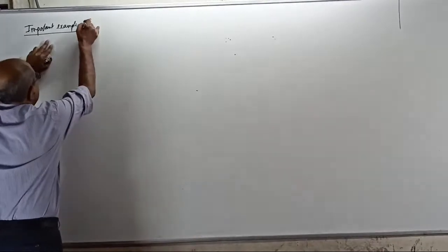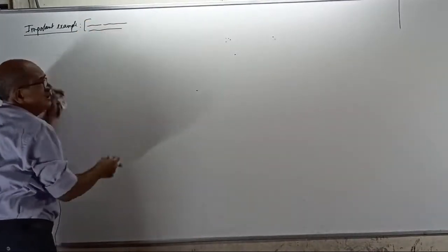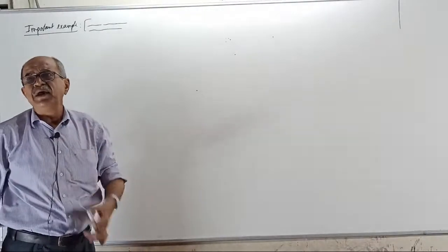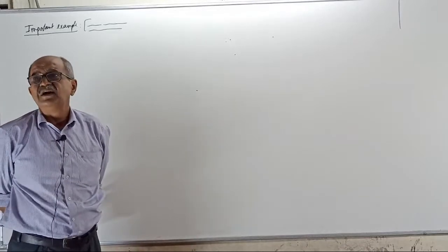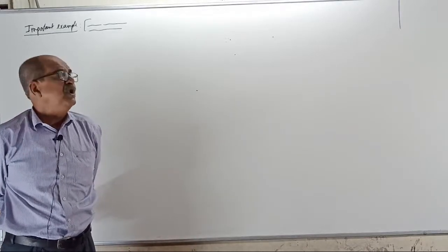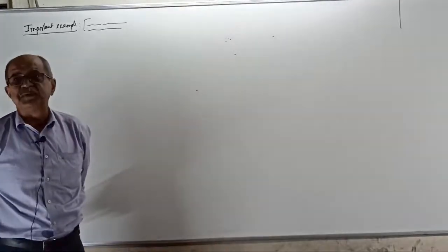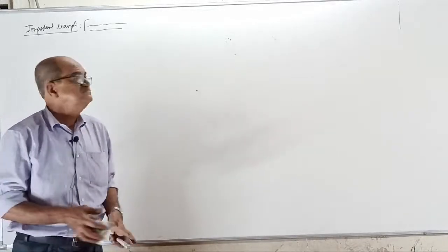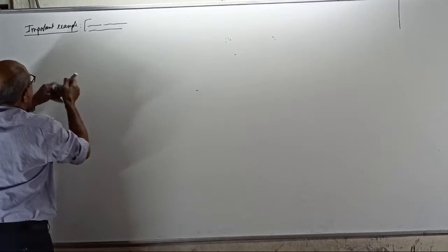To understand thoroughly the limitations of Euler's formula or Euler's theory, it has got limitations. Every column, Euler's formula is not applicable. It is conditional, so you cannot apply it randomly for any column. You can't apply Euler's buckling load expression and say the column will buckle at this load. No, you can't do it. So for that, one important example, you write here. Now see.